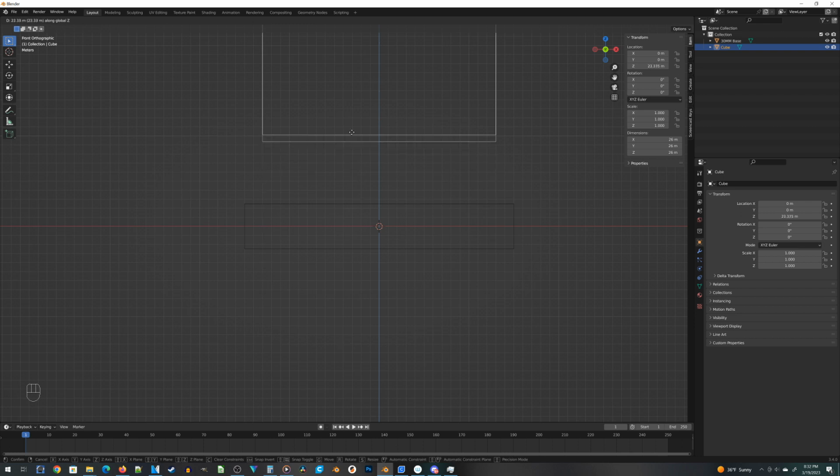And because I want to cut out a 3 millimeter deep hole into the base I'm working on, I want to place the bottom of the cube that I have selected right now about 3 millimeters from the top of the base object. In the background here, you've got a whole grid of little light gray squares. Each one of those light gray squares is about 1 millimeter. So we can kind of eyeball 3 pretty easily from the top. 1, 2, 3 is right around there.